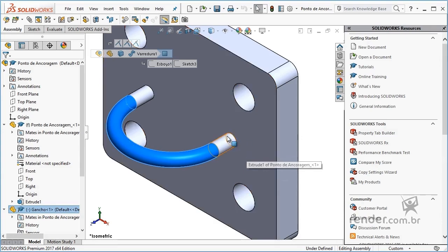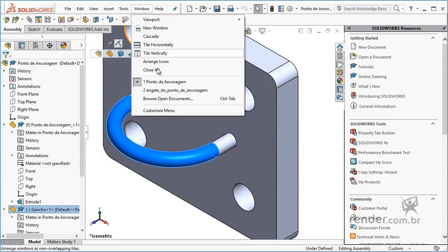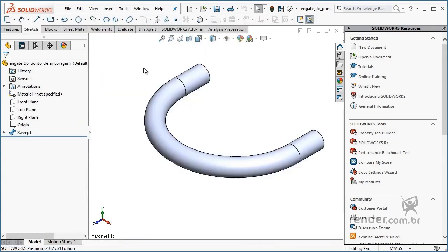Our goal in carrying out this analysis is to know SimulationXpress and see how this model will behave when applying constraints and forces. The applied load will be 2,000 kg force, which is equivalent to approximately 19,615 newtons.